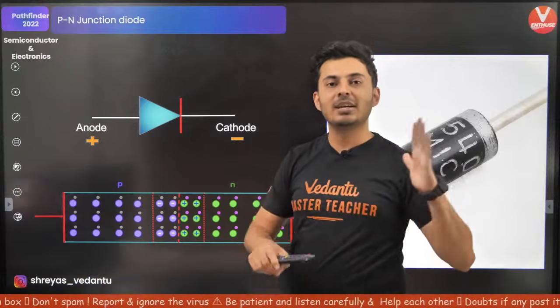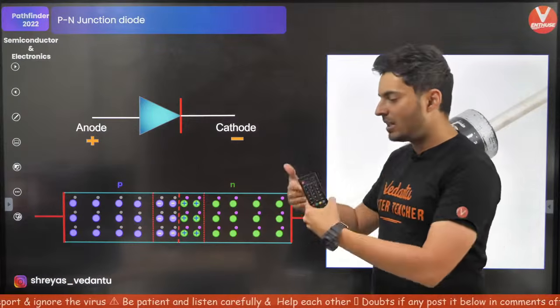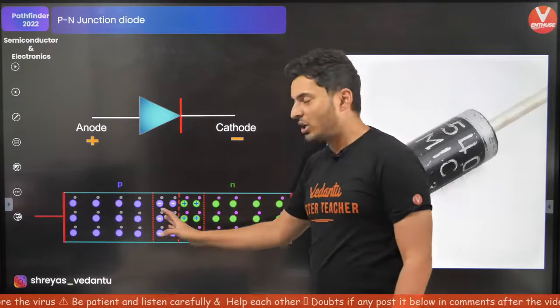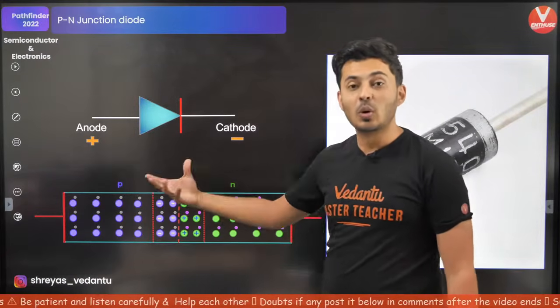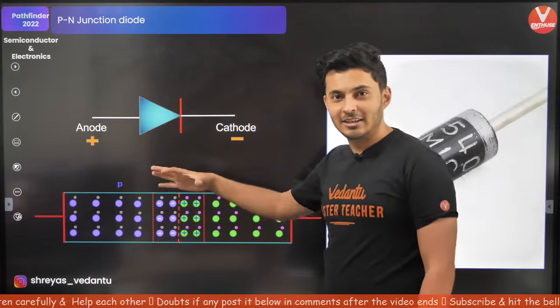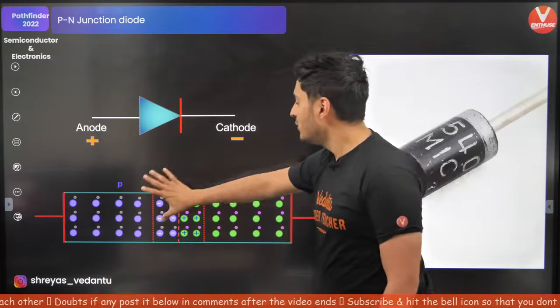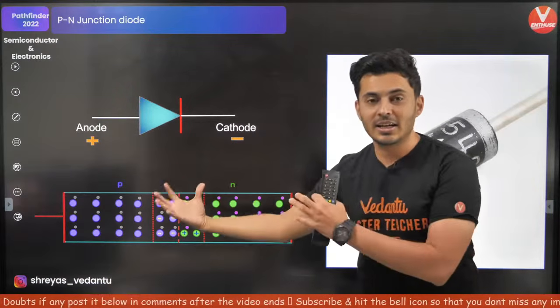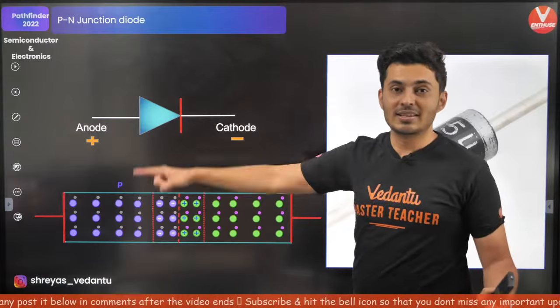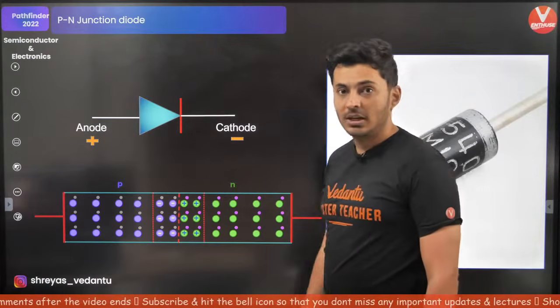Reverse bias is when it blocks the current. So P type and N type are merged together. They form potential barriers. P has more holes, N has more electrons. Recollect, there is diffusion current and drift current, and when the forward bias is active, the diffusion current overtakes the drift current, and that's why the current circulates in the circuit, because of this particular diffusion.